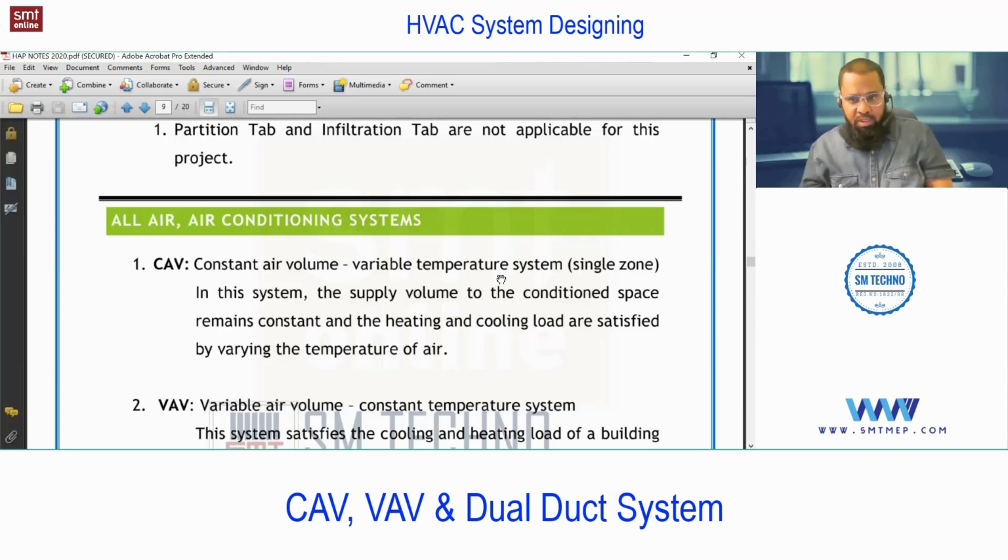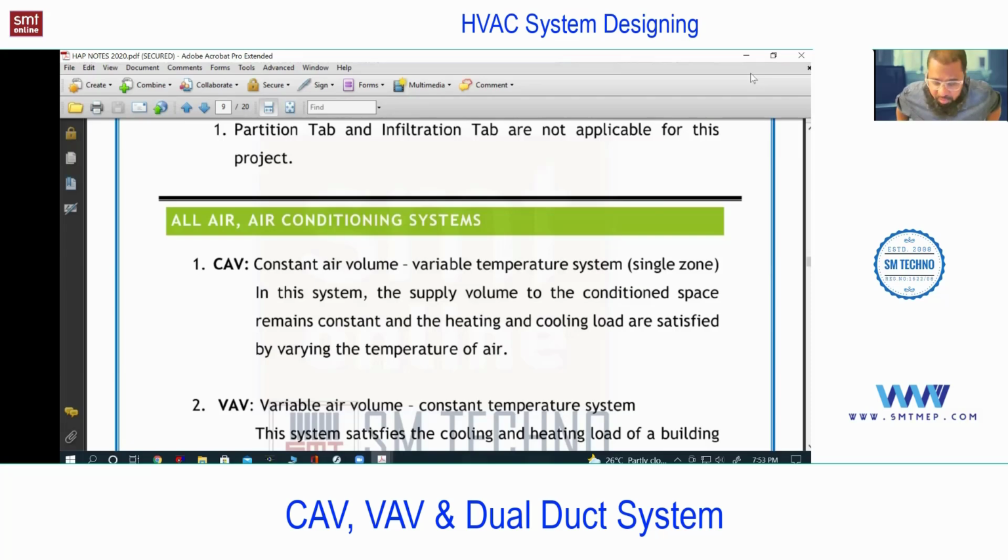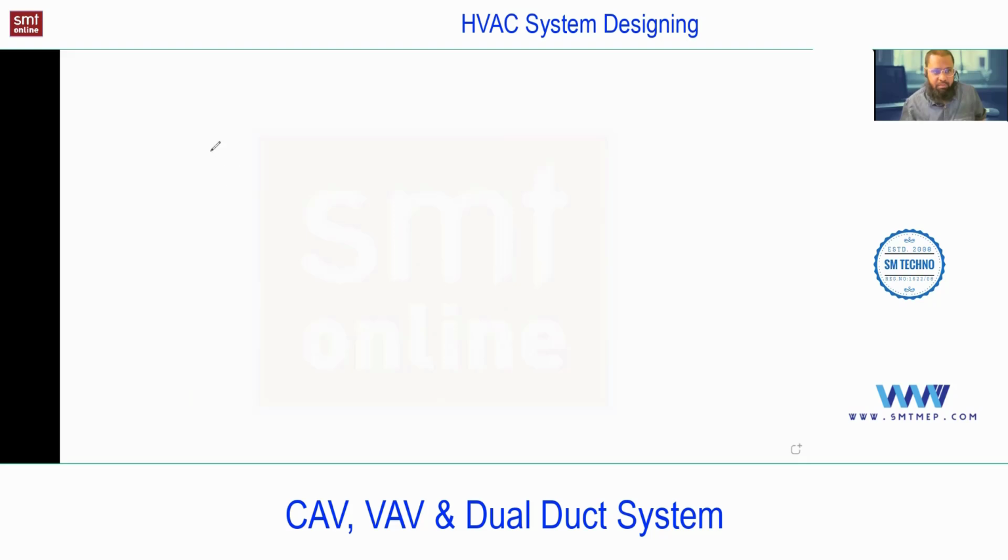Next point, you can write zone. Zone refers to thermostat. Thermostat means what? In bracket, controlling. I'll explain. We have different possible cases for the zone. Here on screen, for example, case 1. In this room, I'm going to install one split unit with outdoor. So this is space 1, and for one space, one unit. So this is zone 1, means one space, one unit. Because for this split unit, separate controlling, separate thermostat remote is there. This is one case.